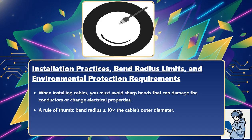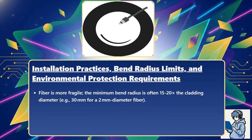A rule of thumb: bend radius greater than or equal to 10 times the cable's outer diameter. For coax, a 0.5-inch cable should not be bent tighter than 5 inches. Fiber is more fragile. The minimum bend radius is often 15 to 20 times the cladding diameter. For example, 30 millimeters for a 2 millimeter diameter fiber.